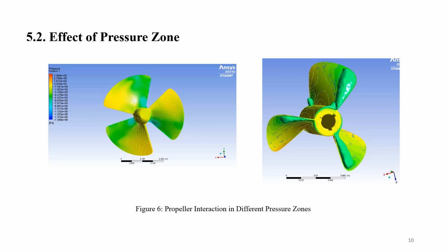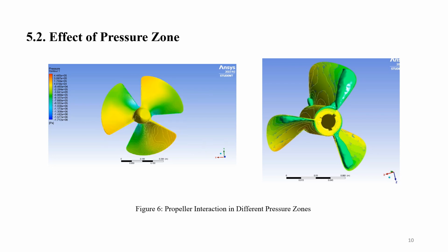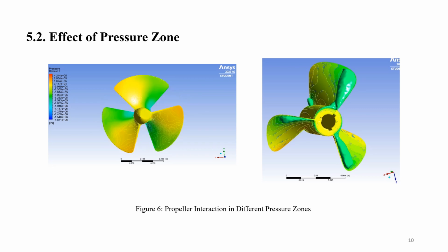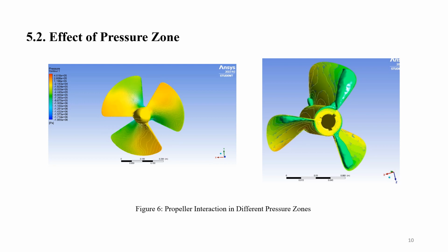The simulation using the Schneider cavitation model and the multiphase approach enables a detailed examination of cavitation phenomena over time. Visualization through isosurface of vapor volume fraction offers a comprehensive understanding of cavitating zones at different stages during the 5-second simulation, providing valuable insights into the dynamic behavior of the fluid around the propeller.